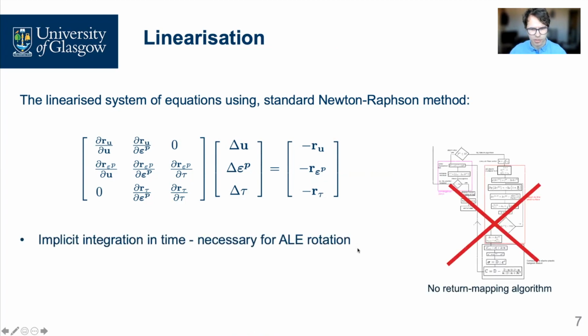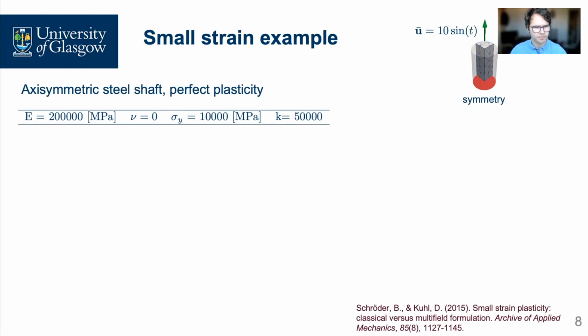But in our approach, any of these algorithms are not necessary because we are solving for displacements and plastic variables simultaneously in one monolithic Newton-Raphson scheme. One more thing to note is that we also incorporate the implicit integration in time, which will be necessary later for the ALE formulation for rotation.